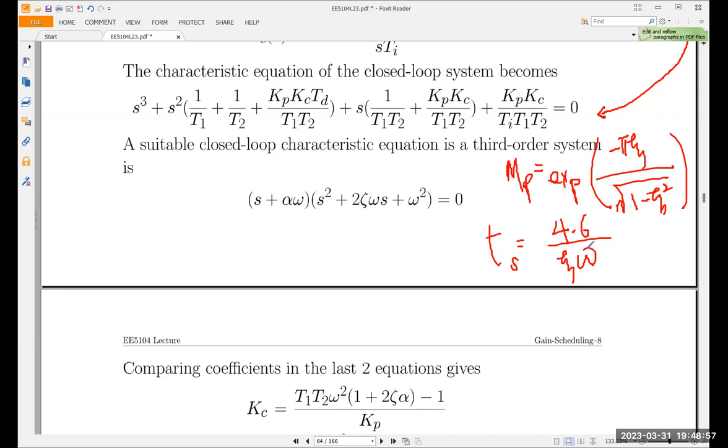So it's 10 times to the left of this. Then this one, even though it's there in the maths, will not affect your settling time and your maximum overshoot. In fact, it doesn't need to be 10 times, 5 times, 4 times is already good enough. So which means if the real part of this is -3, you choose the real part of this to be -12. It basically doesn't really affect this much.